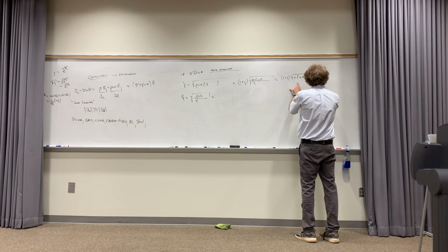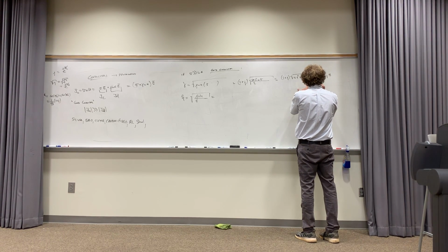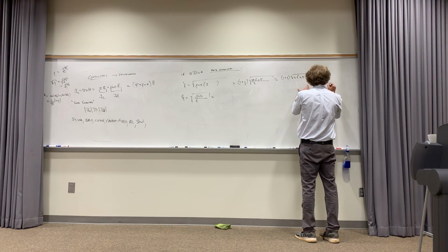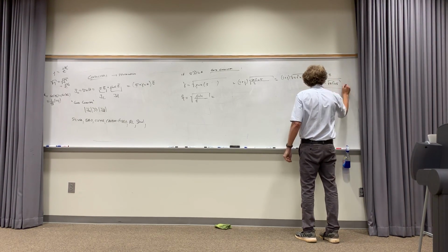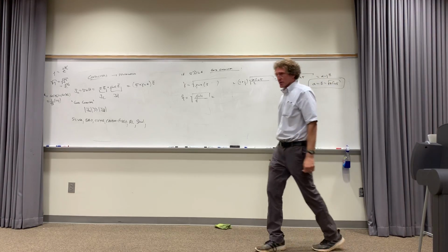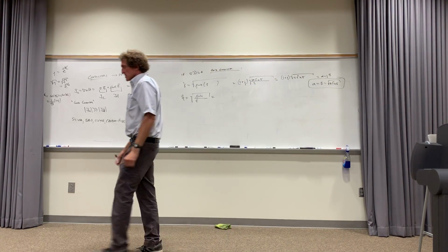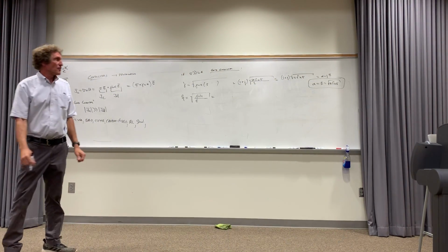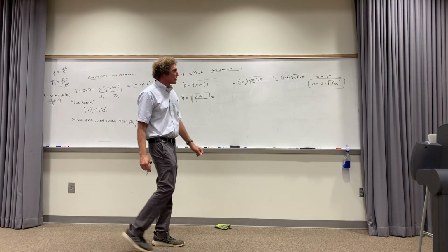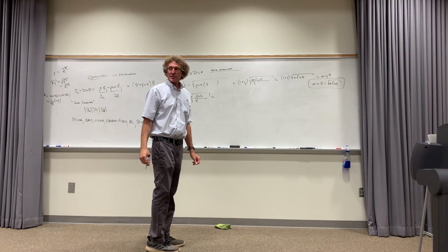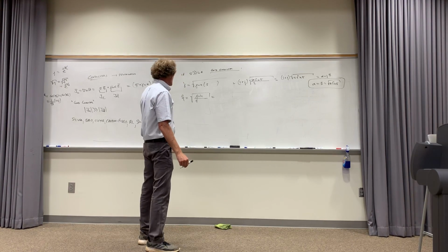And that's equal to alpha plus j beta, which means that alpha is equal to beta, which is equal to the square root of pi f mu sigma. And this is important in a very good conductor, a good conductor, where sigma is much greater than omega epsilon. Alpha is equal to beta is equal to square root of pi f mu sigma. This is very important. Now what about this?